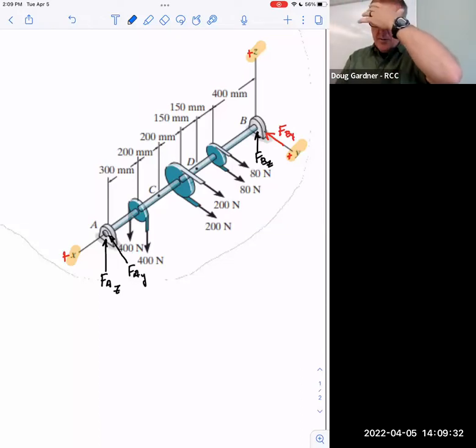And the 200 and 800, what are they spinning it around? They're spinning around the Z. If you do moment around Y, would that be the right hand rule? Yes, that's exactly right. It would be positive. When you say Y, if it's around the Y axis, there's the positive Y, that's my thumb, and so rotation in this direction is positive.